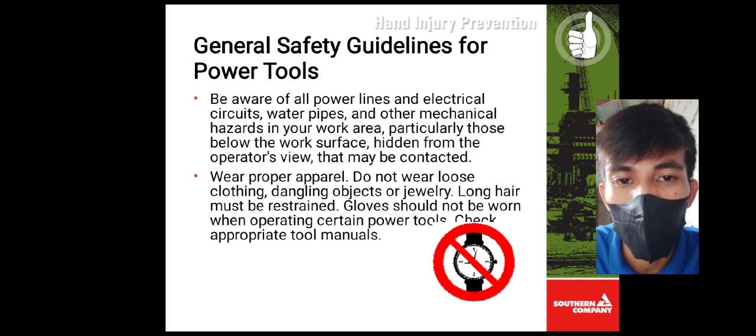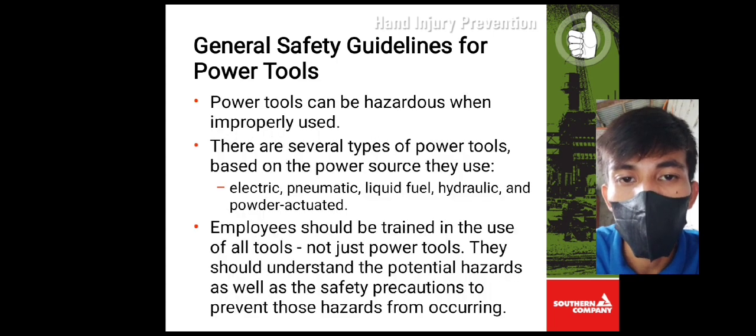Wear proper apparel. Do not wear loose clothing, dangling objects, or jewelry. Long hair must be restrained. Gloves should not be worn when operating certain power tools, so check the appropriate tool's manual. Power tools can be hazardous when improperly used.